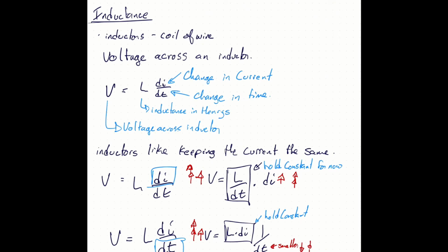So what's causing these arcs? Like, why do they stretch out like that? Where are they coming from? Why are we getting that sort of behavior? Why doesn't the power just go out? And the answer to that is inductance.